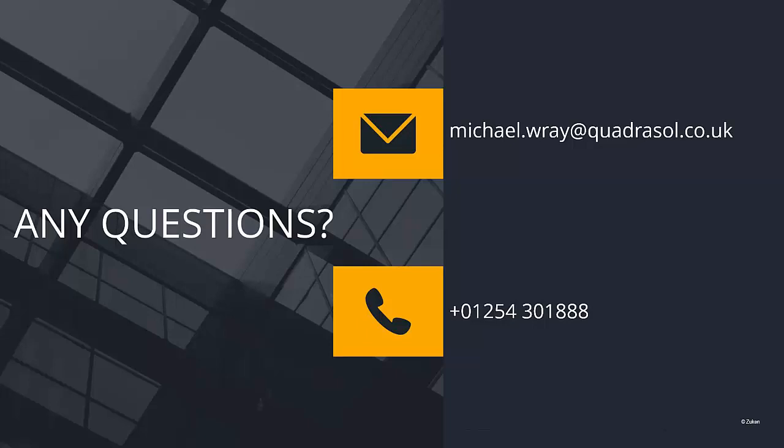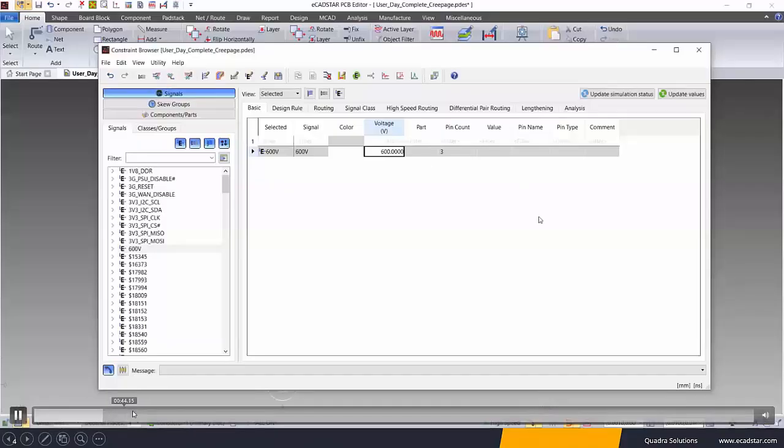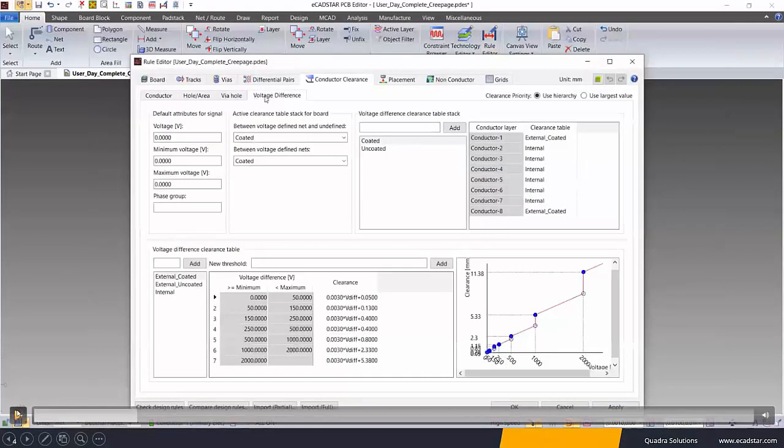Sarah, I don't know, have you seen the second question from Michael, or have we got time? Or I'm just going to whiz through this video and just answer the question about here. Okay, so you can see here, you've got your clearance tables here, so external coated, internal, and then I've assigned those rules to a conductor layer here. You can see, so this is an 8-layer design. So I hope that answers that question.